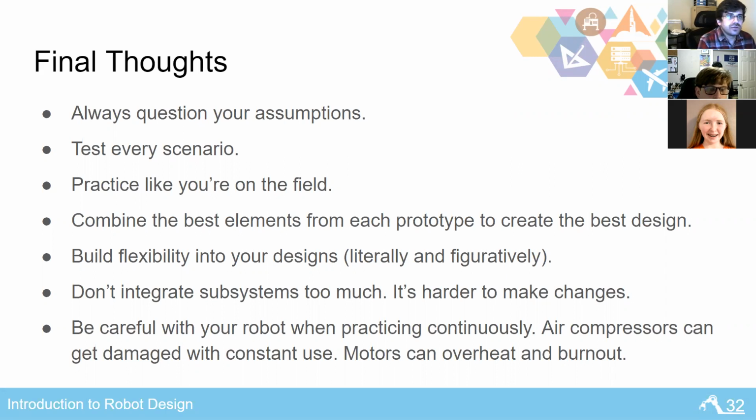So in order to get around that, we look at this idea of flexibility or compliance. If you have a squishy ball, for example, you can rely on that ball to squish a little bit as you bring it into your robot, and you can have a pretty rigid mechanism knowing that the ball is going to take up that tolerance that I'm talking about.